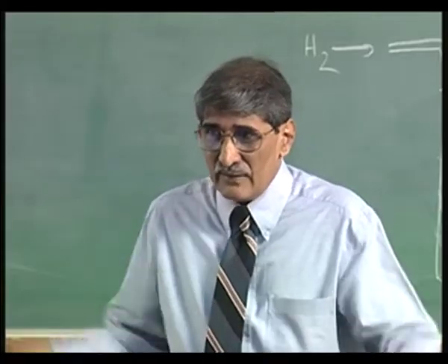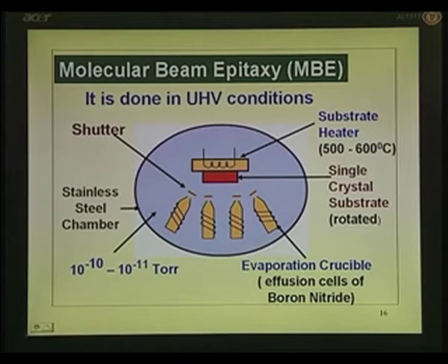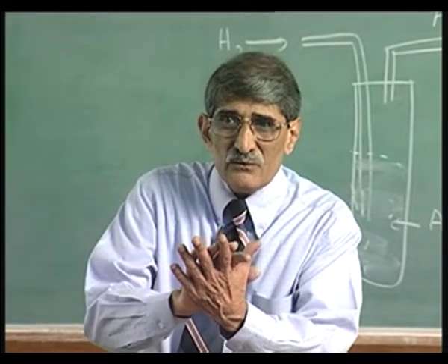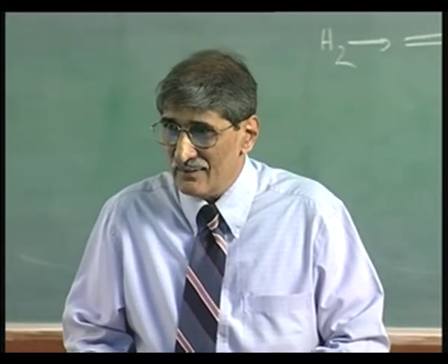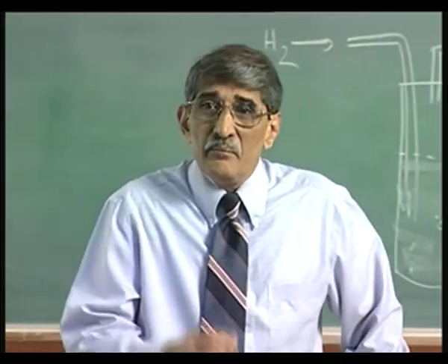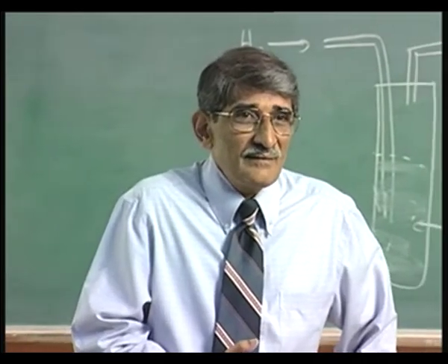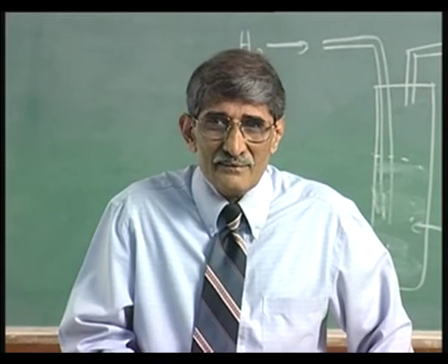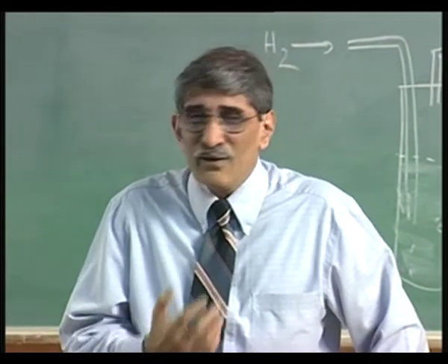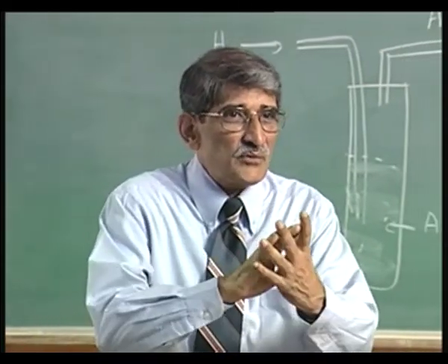So, to get inside, to put all these things, wafers, loading, etc., you need those things. So, when you close a chamber like that, there will be a gasket. You can't use any gasket that you like. So, what you use will be metal gaskets. Metal gasket, what metal? Hold your breath, gold.